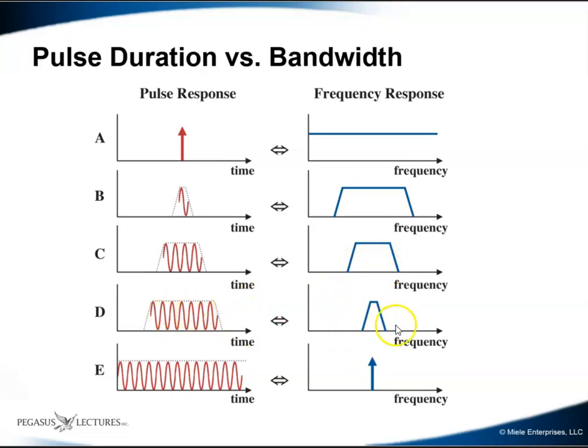Continue to increase it, our bandwidth continues to narrow, and if we use continuous wave ultrasound that is always emitting sound into the body, we get an infinitely narrow frequency, or a perfect frequency response for what we're emitting. We can do this, but we can't image with it. Okay, so we can't image with a continuous wave ultrasound, but we can get a perfect frequency response from it.